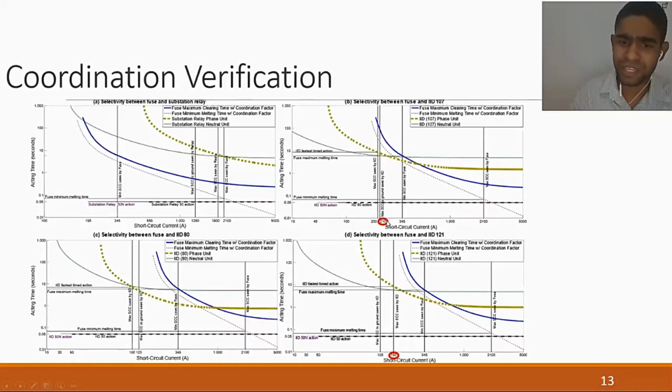Finally, we can observe here that this maximum short circuit current at branch 107 is not twice the short circuit current in branch 121, even though the power injection in this branch is more than double the power injection in this branch, which means we are limiting the current injection of the solar farm and the wind farm, which has impacts on the pickup currents of the IIDs.